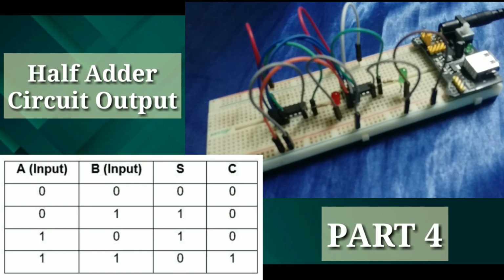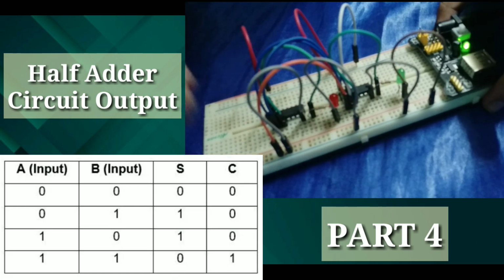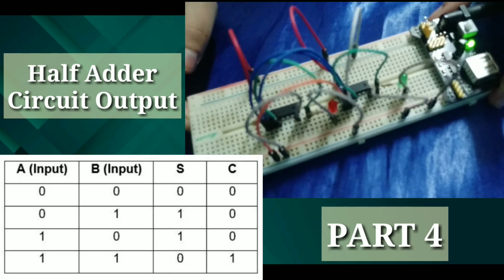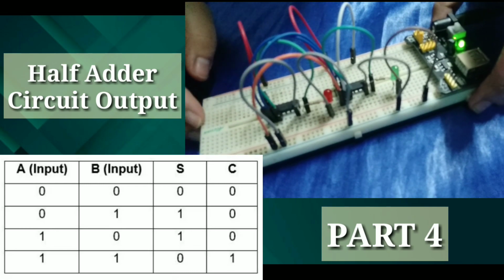Now, for our truth table and for our outputs, let's turn on our voltage supply. If both input A and B are at 0 or connected to the ground, as you can see, our output for S is 0 and our output for C is 0 as well.